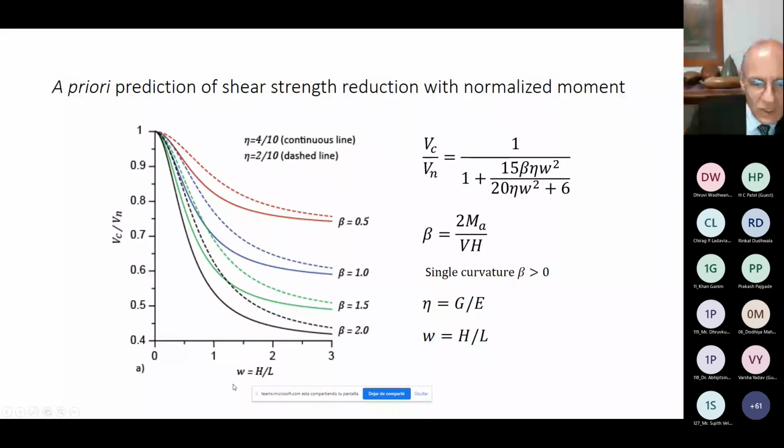But as soon as you start to get slender walls, the effect of the moment increases. But it doesn't keep growing, it's asymptotic. So this behavior is very interesting. It's consistent, as we will show. I won't show it here because again, it will take some time. But anyway, here are the main parameters. Again, these are the material properties, the aspect ratio, and the normalized moment.